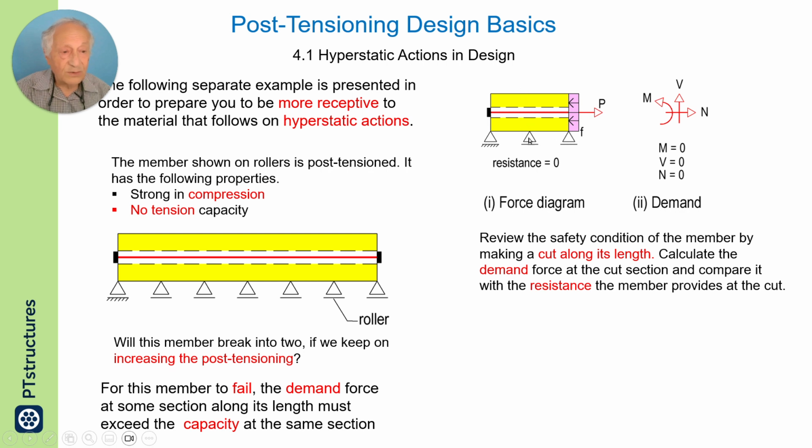All the vertical goes down to the support. The force which is anchored here goes directly to the member. There is nothing on the left which will contribute to the demand. Therefore, there is no requirement for resistance to be developed at the face.